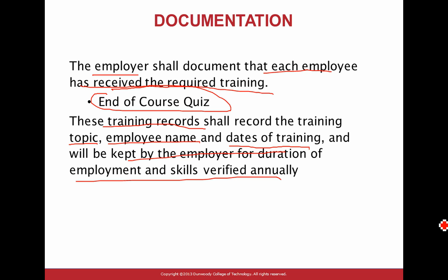One of our students at Dunwoody, a first year apprentice, was working on a 3,000 amp switchgear, I think for People's Electric. They were working energized, no PPE, 3,000 amp, 480/277 switchgear, tying a new circuit to it. And somehow they got an arc flash; something got dropped into that switchgear.